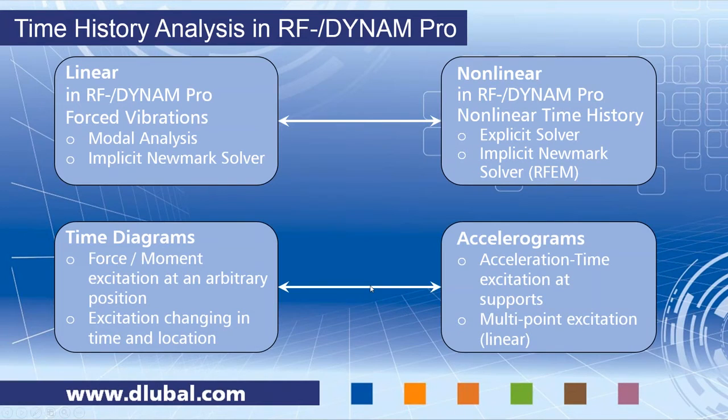We further distinguish between the time history analysis of time diagrams and oscillograms. The time diagrams can be defined as tabulated values, as a periodic function, or you can enter a function term directly in an added field. You define loads and load cases to define the location of the excitation. So this makes it very flexible. You can define nodal, member, and surface loads, or even free or generated loads. So you can excite the structure everywhere, wherever you want.